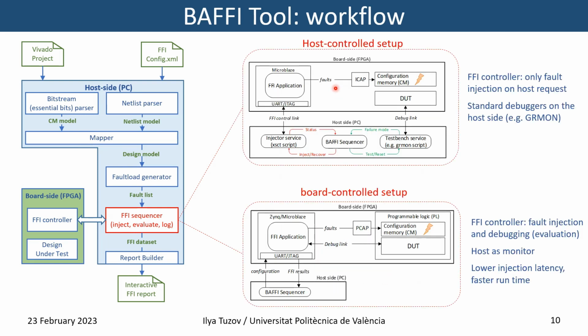The sequencer supports two alternative setups. The host controlled setup is used when we need a standard debugger on the host side. In this case, the on-chip FFI controller is only in charge of fault injection, but the design under test control and evaluation of fault effects is performed on the host.